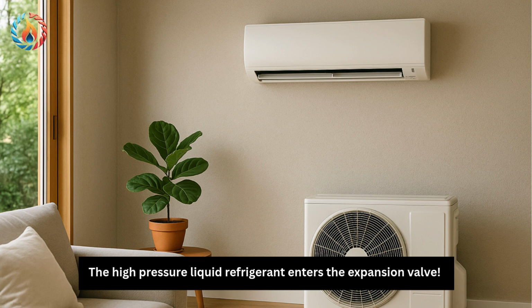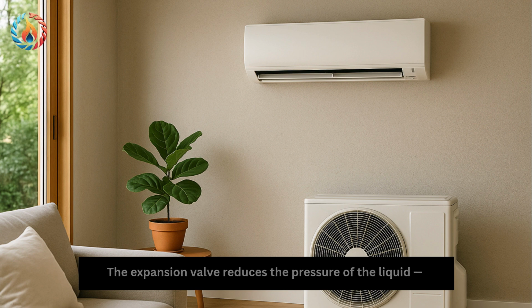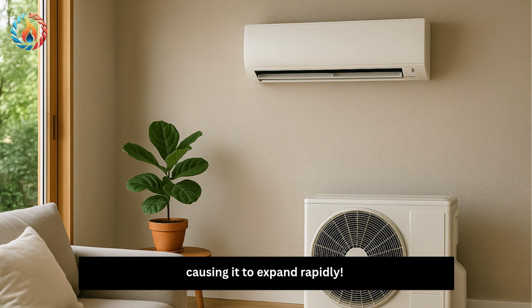The high-pressure liquid refrigerant enters the expansion valve. The expansion valve reduces the pressure of the liquid, causing it to expand rapidly. This sudden pressure drop causes flash evaporation. Some refrigerant instantly turns to vapor.